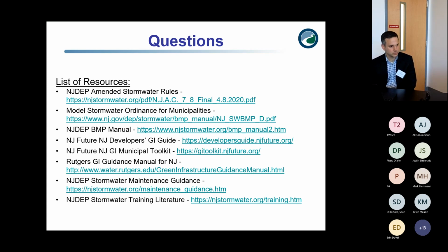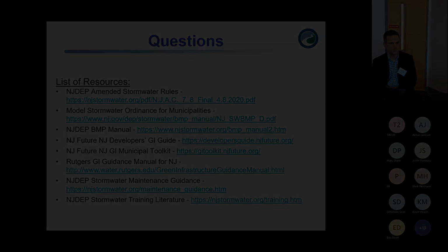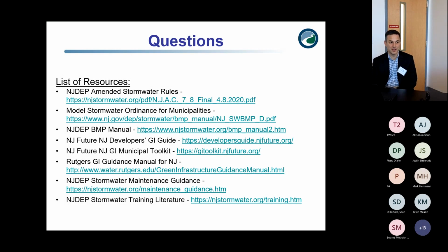Yes. We see the need to reevaluate green infrastructure systems that rely on infiltration when sea level rise gradually raises groundwater level below those systems. And there's going to be flooding very frequently in those areas. But it doesn't mean that you can't use green infrastructure in those areas. It's something that you have to plan for. And it's the kind of thing where you want things to work to provide some benefit now, even if in the future it's going to have some reduced efficiency.